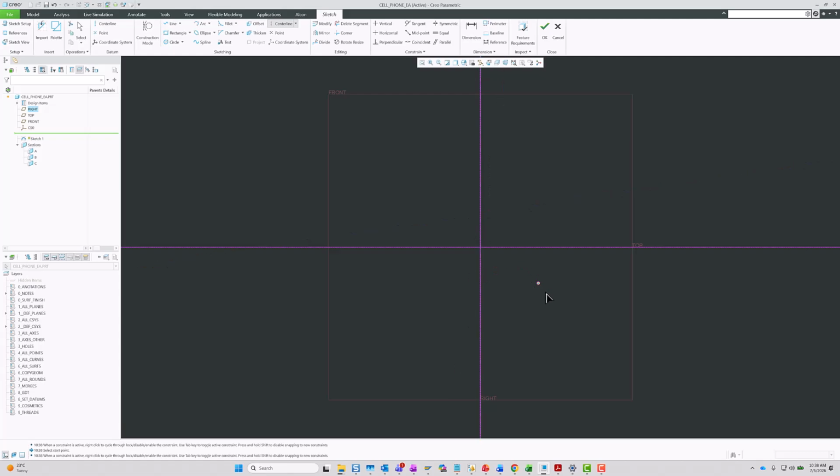All right, let's start with a line here. Then I select it and click Mirror, and select this line. Then I click Arc. One click, two clicks, and move it a little bit down. Don't move it too far, because it will lock as a semicircle. Move it a little bit down like here, and click with the left mouse button.